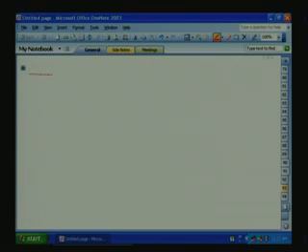Last class we were talking about how to generate a three-phase waveform based on individual pole voltages with a 120 degree phase shift, and for three-phase how to suppress the triplen order by removing the neutral. So, we will again start from there. Let us draw the waveforms once again.